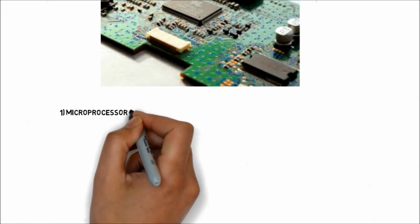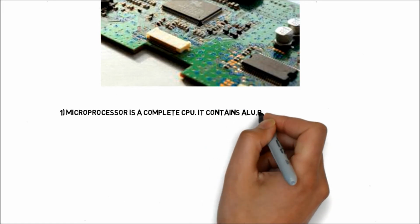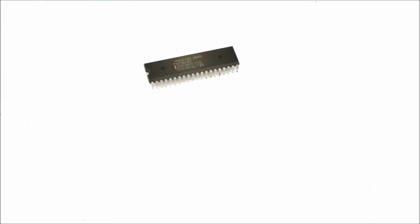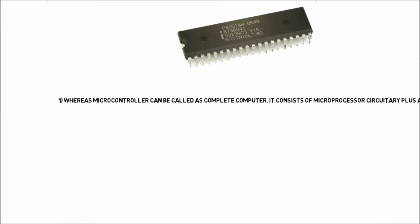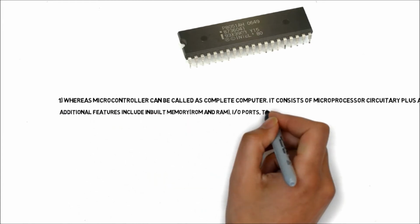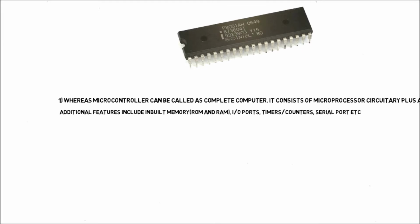The first difference, what do you mean by microprocessor? It's a complete CPU. It contains ALU, registers and control unit. ALU is arithmetic and logical unit. Then talking about microcontroller, it's just a mini computer, and it is nothing but a microprocessor plus additional features. The additional features include inbuilt memory like ROM and RAM, timers, counters, serial ports, then input output ports, etc.